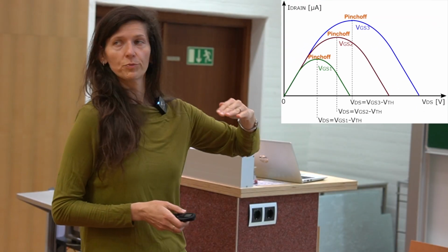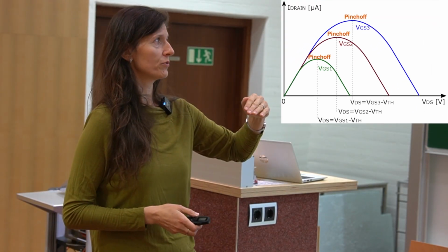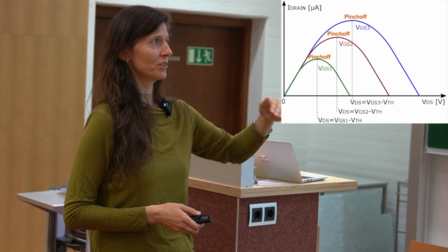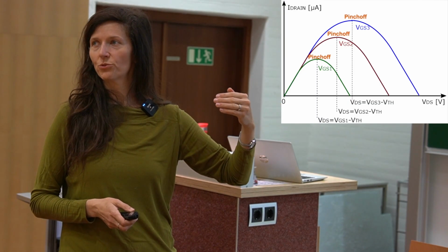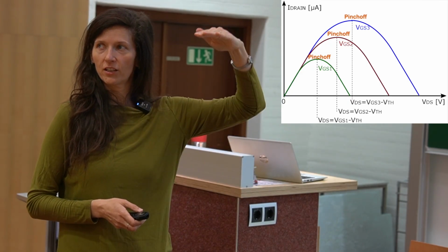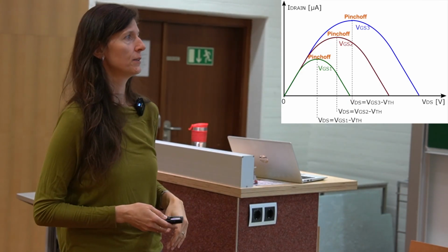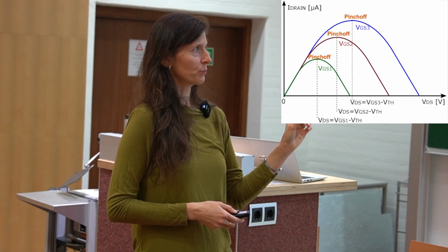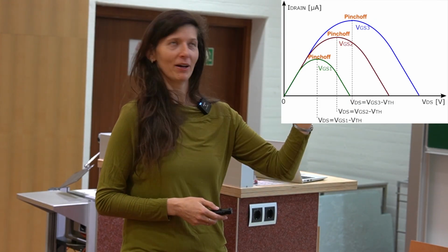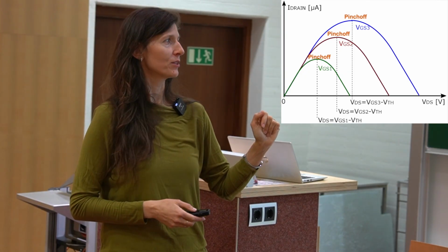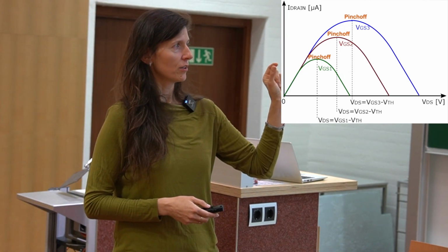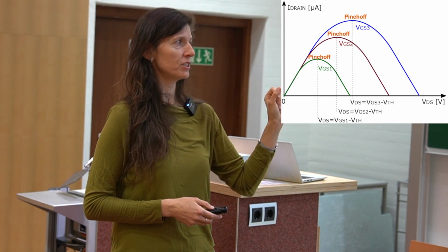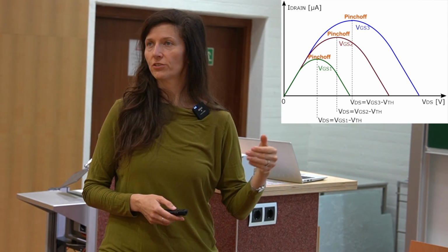And to move between the characteristics of the MOSFET transistor, these so-called output characteristics, what we do is change the gate to source voltage, and the current is increasing. This characteristic pinch-off point, where the maximum of the parabola takes place, is equal to VDS. So the VDS at that point is equal to VGS, gate to source voltage, minus the threshold voltage.